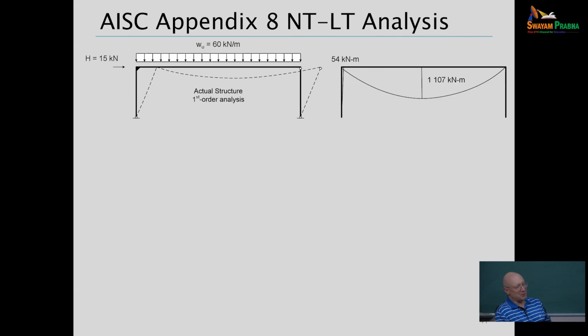But for the left-hand end of the roof girder to rotate as a simply supported beam requires that the frame shift to the right under the gravity load. Here it's just a dinky little market shed. But as I mentioned yesterday, the Lake Placid ice skating arena, where the U.S. hockey team beat the Russian national team back in the day, is a similar type of system. We could sketch that out similarly.